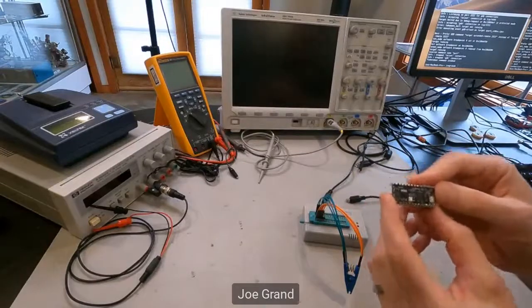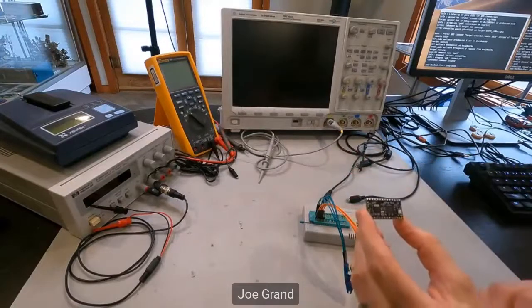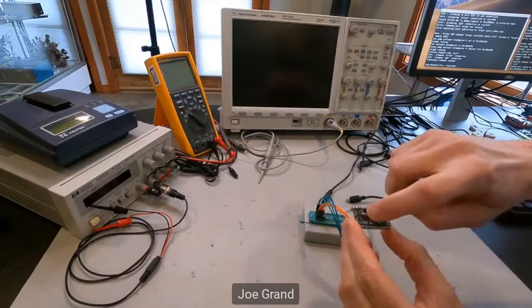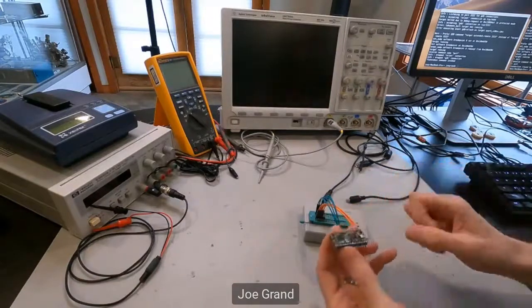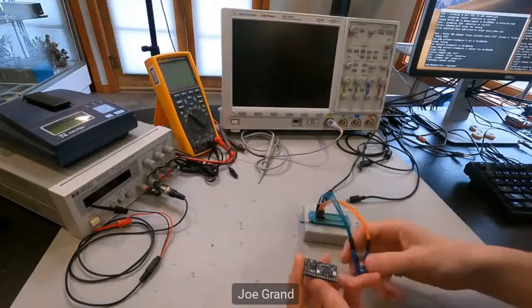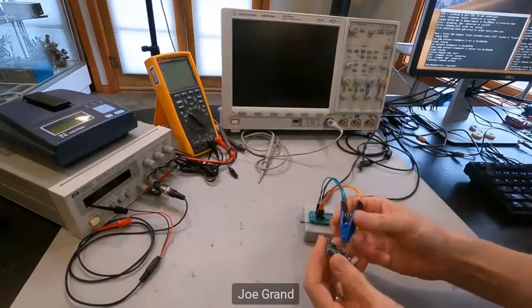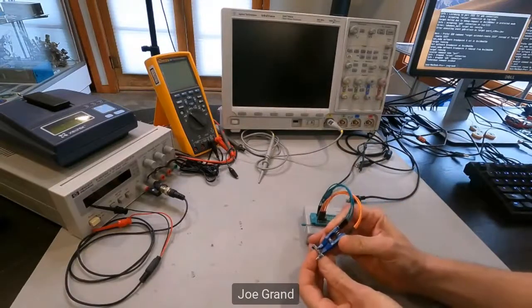This is a Lo-Five R1. It's a RISC-V based device that uses a SiFive FE310 chip. And then the bootloader and the code is stored on this external chip. This is also really cool because it's a low-powered device, meaning we don't have to worry about powering it externally before we use our device programmer. The programmer has enough current capability to read the chip while it's still in there.